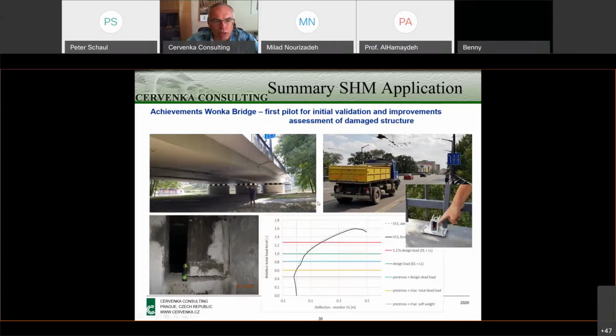So in order to do that, of course, this measurement had to be calibrated. These are pictures from another bridge, but same approach was used in that German bridge. So first, this monitoring system was calibrated by some trucks with predefined weight. And there was a sensor, also laser sensor, counting the vehicles passing.